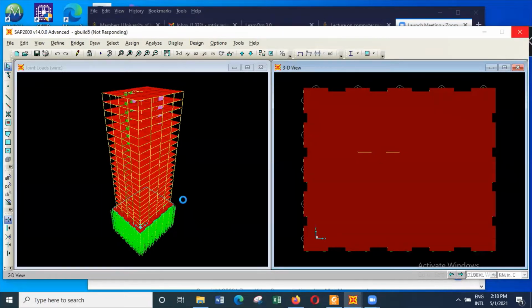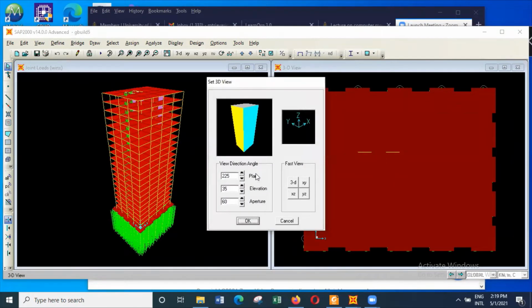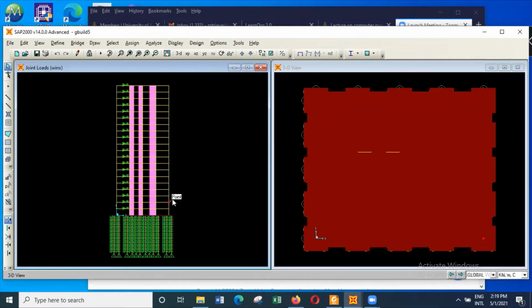Okay, now we are going to see what situation can arise with raft foundations. This is a 20-story building. Generally, when you are going with raft foundations, it would be limited to about 6-7 stories, so maximum 8 to 9 stories if you get good soil conditions. So we'll consider something like an 8-story building. I'll use this building and convert it to an 8-story building. We'll just consider 10 stories for the time being. So 8 stories, maybe okay. 2, 4, 6, 8.